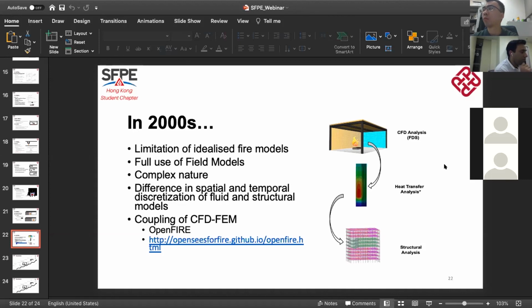Yes, if we use it in the design stage, and we want to find out the worst fire scenario, then for structure analysis, maybe we just need the highest fire temperature. Yeah, usually they do that as a safety factor. They consider high temperature and put some safety factor like 10%, 20%. This is what the structure engineer actually does. That's why you can see the standard fire is still quite famous, because it just gives the very maximum temperature. So you already include the safety factor there. But of course, that's not reality.